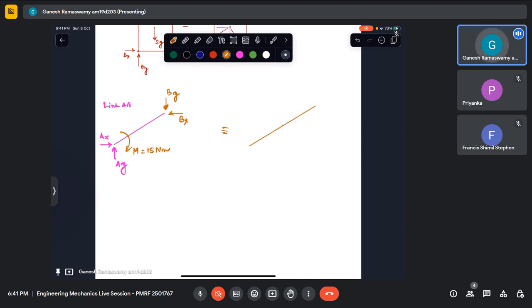So now comes the key. Now we know that this will actually be having some rotation, right? And then similarly, by virtue of this, I have m_AB a_G tangential, and then one component like this, m_AB a_G normal.